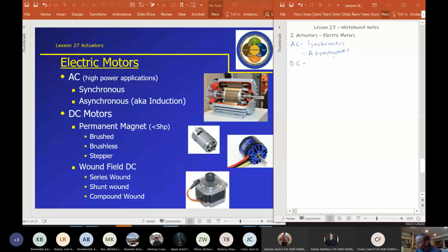That's what's used, for example, in quad rotors. They're high efficiency. And we have stepper motors. What distinguishes these types of motors is that they have a permanent magnet, which is what it sounds like, a magnet that is permanent. It doesn't move, it doesn't change, and that interacts with electrical windings and the magnetic field generated by the current flowing through those wires.